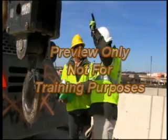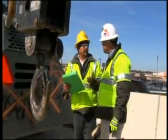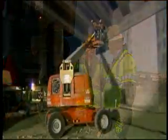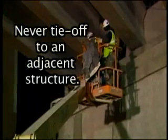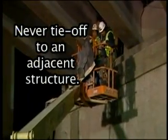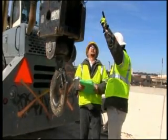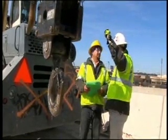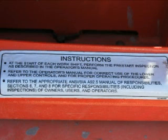If no anchor point is available, it is up to the on-site job supervisor to determine the best point to tie off. Tie off to an adjacent structure is never allowed due to the possibility of being pulled out when the lift is moved. Your employer and the manufacturer of the lift in use will provide more precise fall protection rules and guidelines. Manufacturer's guidelines must always be followed.